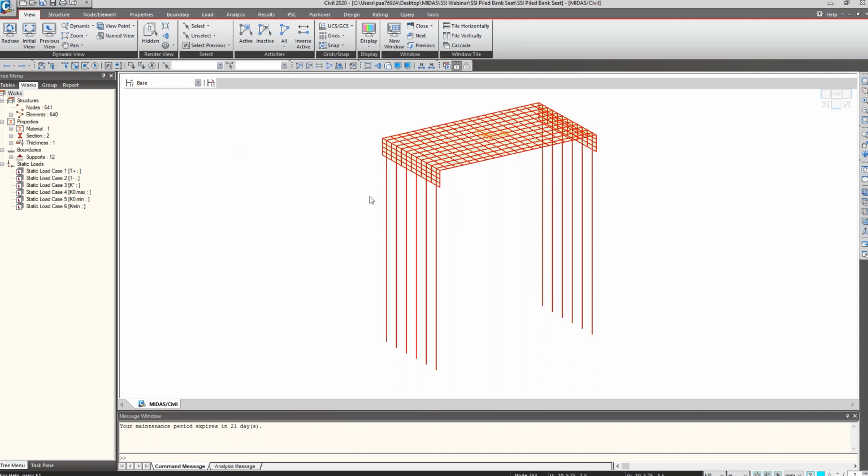So we have the piles at the moment, but what we don't have on this model is the stiffness of the ground around the piles, and that may be very important in identifying these movements, because if the soil is very stiff, it's going to prevent the deck from expanding, and then we will have a smaller value for the expansion and the contraction, and then we'll have a value for the K star. If it's a very soft soil, then it's going to allow the deck to expand and contract with a bigger magnitude of movement, and then we'll have another K star. So getting the soil stiffness around the piles properly is very important.